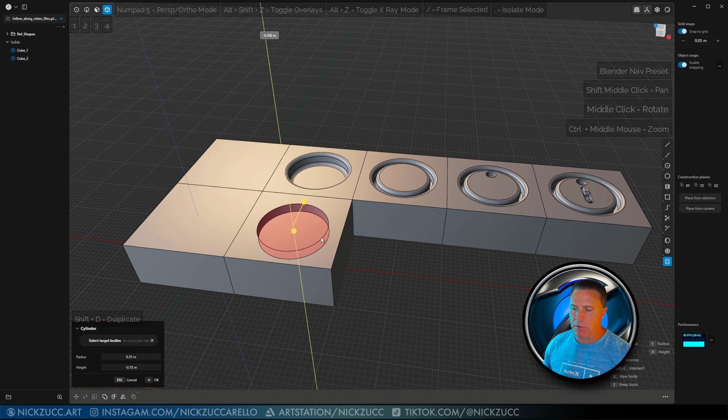And then this tool lets you drag down, and it automatically is going to be in this mode where it's doing a difference. If you look in the bottom right-hand corner down here, you can see that there's a bunch of different hotkeys and things that you can do with this. And because I started dragging this off of the surface, it recognizes that I'm going to do some kind of difference with this. Now, I don't have to do a difference. I can drag up, and that will add the shape to it. If I drag down, it's going to do a negative.